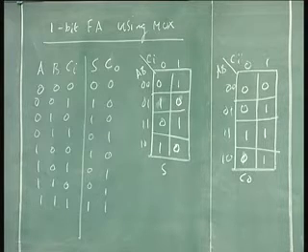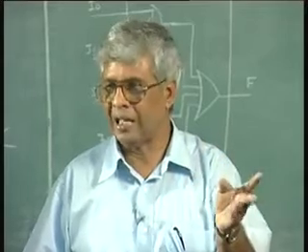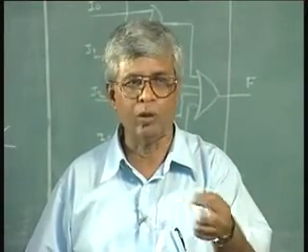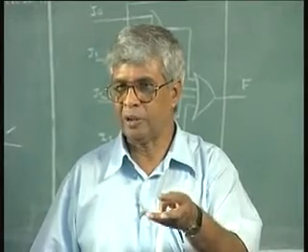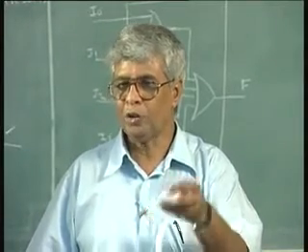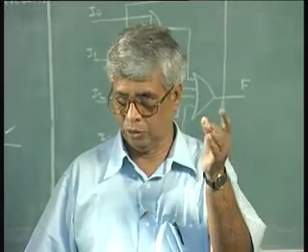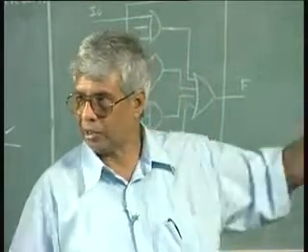So I would like to use a 4-to-1 multiplexer. I need to select two of these variables as selectors. I have three variables, A, B, and Ci. Out of these, I need to select two of them as selector variables. And when these selector variables are 0, 0, what should be given as Ci, so that the output is what is required according to the table.